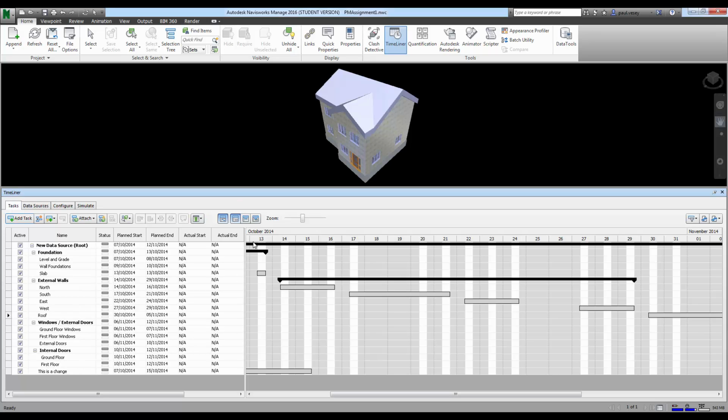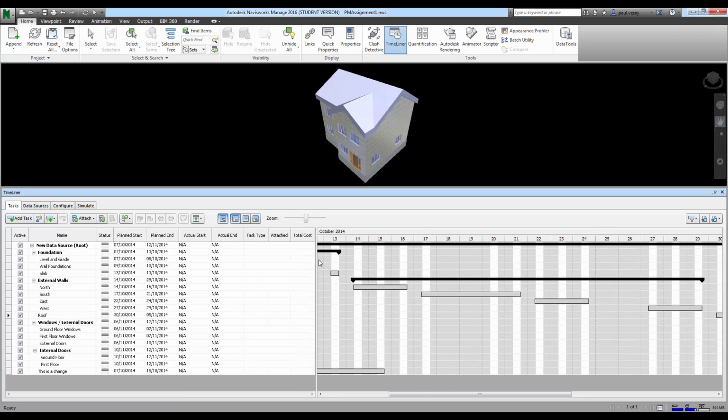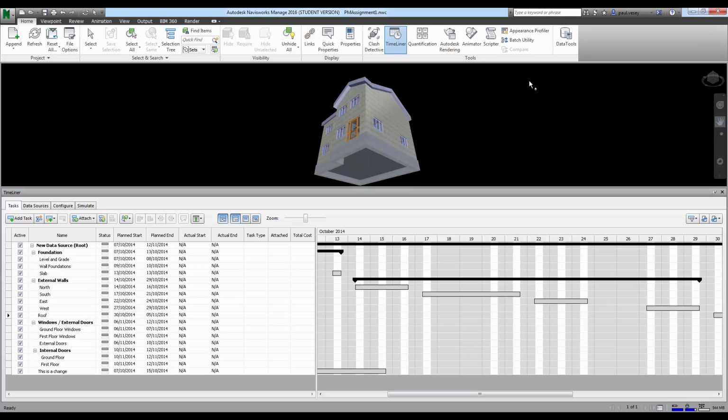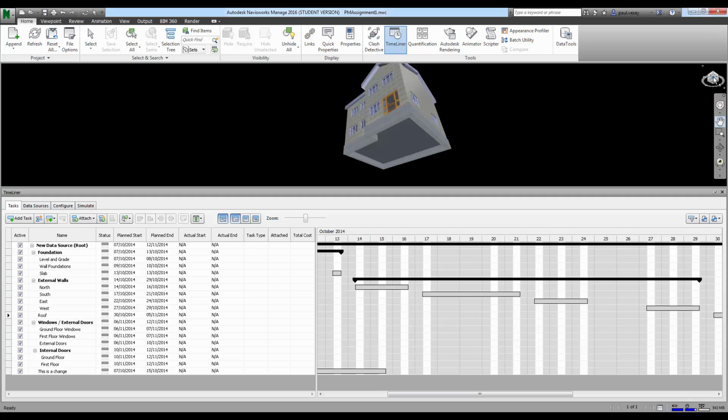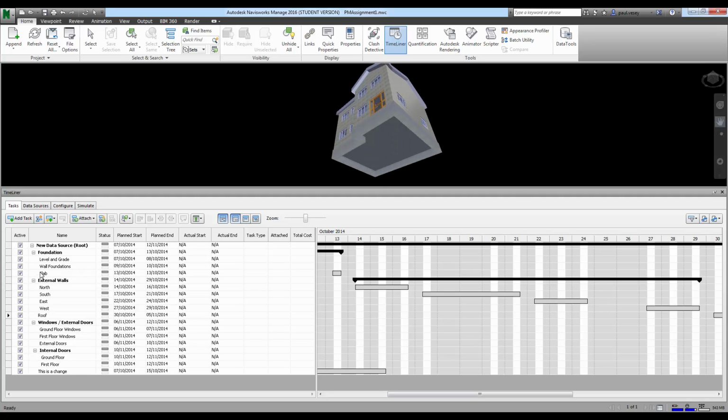Now, we have the data in, we have the house, we have the plan, so the trick now is to simply link the two together. And we do this very simply by selecting the items we want and putting them on. So I'm going to start off with the wall foundations, seeing as they're there. I'm going to go to the select on that, so change my icon from the cursor. And when I click into this space here, it should start grabbing these items. So holding down the control key and just grabbing all of those. So that's all of them.